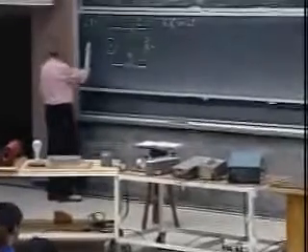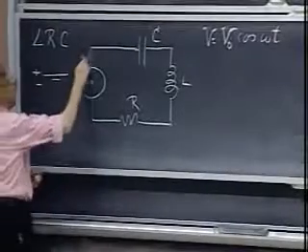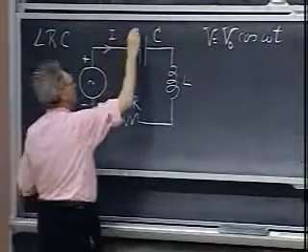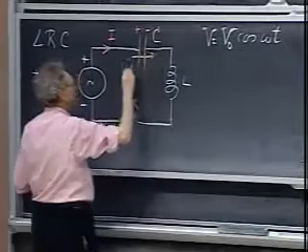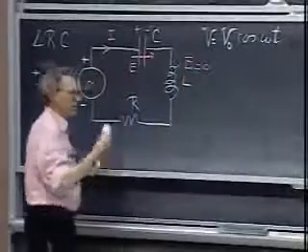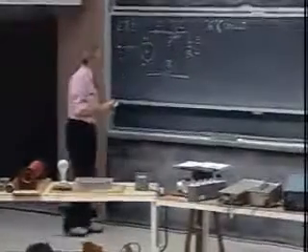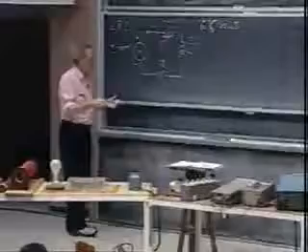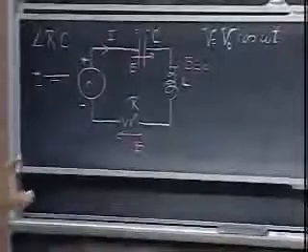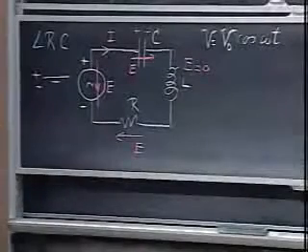In my mind, I think of this first being a battery, whereby this is the plus side and this is the minus side. A current is going to flow. The capacitor is going to charge up. The electric field inside the capacitor is in this direction. The electric field in the self-inductor is always zero because the self-inductor has no resistance. There's no electric field inside the self-inductor, no matter what some of your books want you to believe. Then the electric field in the resistor is in this direction, and the electric field inside the power supply goes from plus to minus, in this direction.